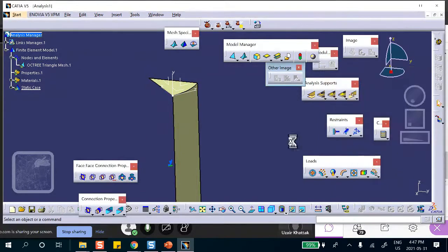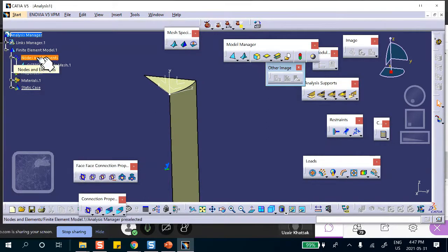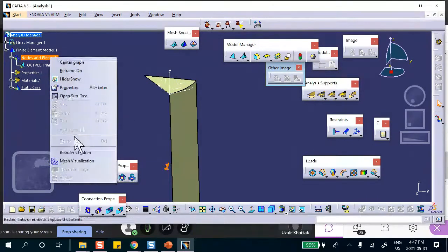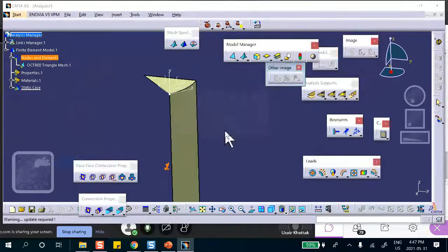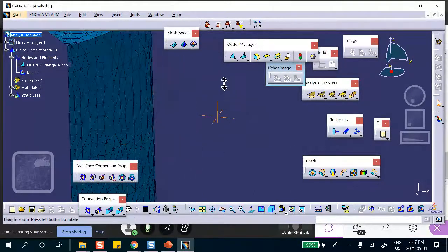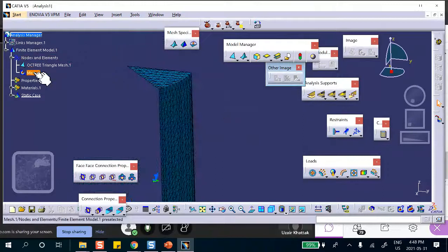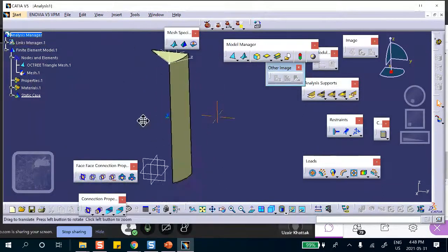Look, you make that thing small, you may have to sit there for a long time, and eventually you have to kill that job. Okay, I'm just letting you know. On the test, unless you're asked to, use default size and sag and linear elements. We'll talk about this thing later. There we are. Okay, fine. This is a little bit finer than the other one, but that's okay, no problem. Deactivate. Let's proceed with the rest of the problem.